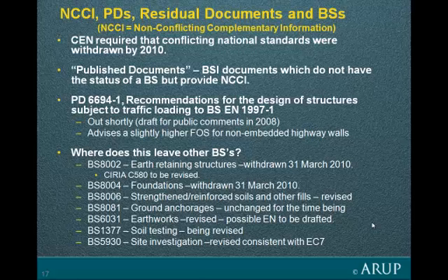On the other hand, when it comes to reinforced soil, BS 8006 has been revised and is still current, and that's been done because the Eurocode 7 has very little to say about reinforced soils. There will be in future a European document, but that's some way in the future. In theory, Eurocode 7 covers ground anchorages, but very inadequately, and therefore the British standard BS 8081 has been retained for the time being.